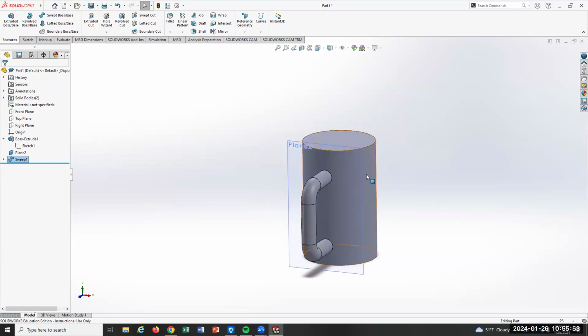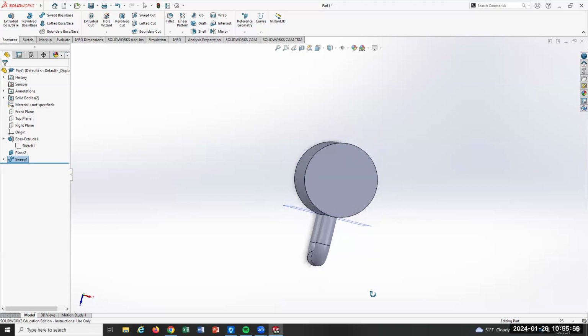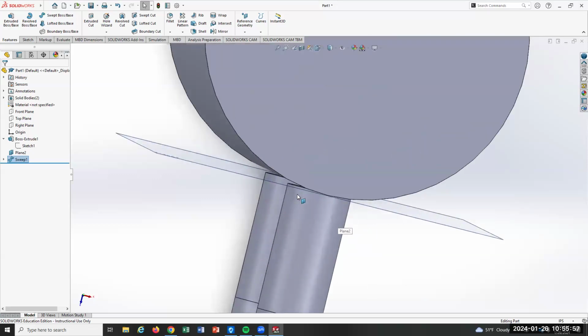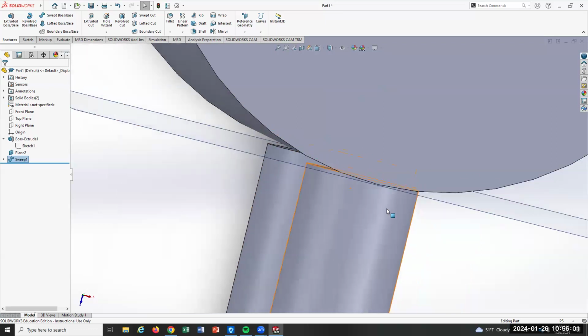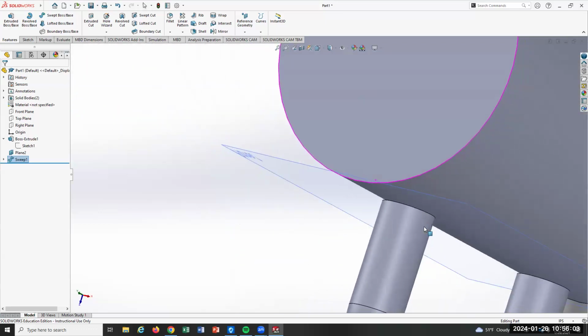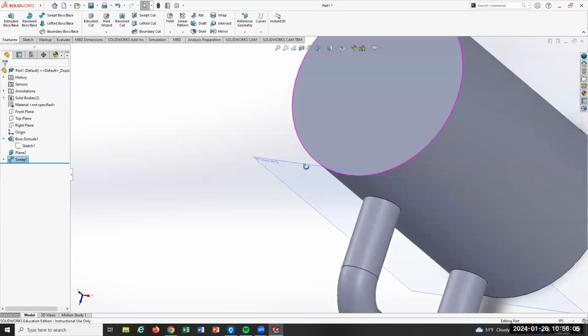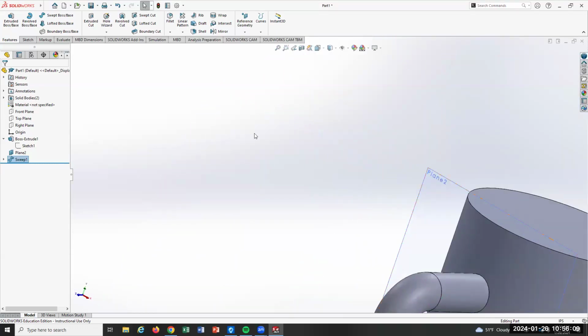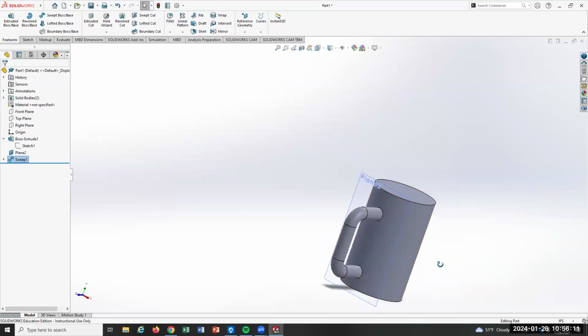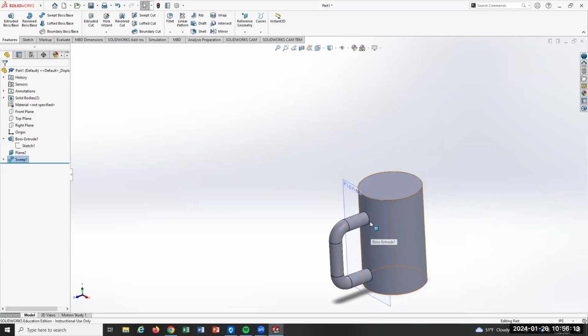All right. So it's close, but it's not perfect, just so you know. This plane, remember, is flat. It's flat. And when I look straight down, you'll see that the handle is not merged with the circular part. It won't do that, right? But I can make it do that. So what I can do is another sketch. So this is just doing it one more time, exact same thing, but this time I'm just going to do an extrusion to the mug itself.